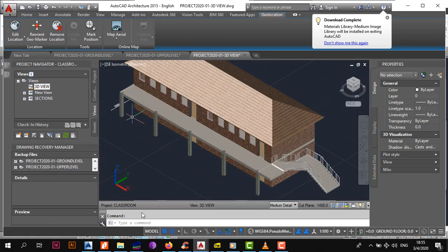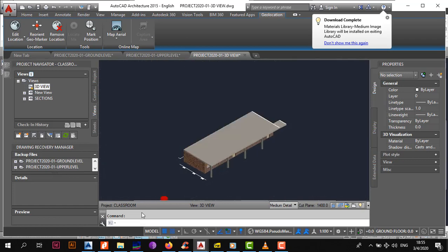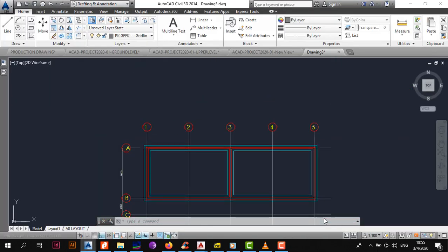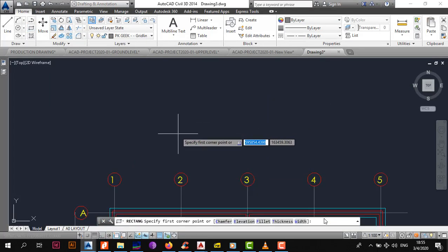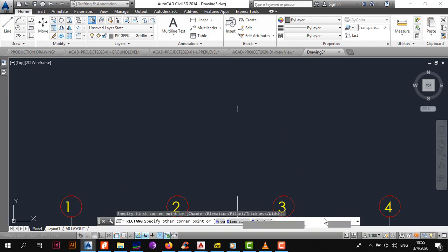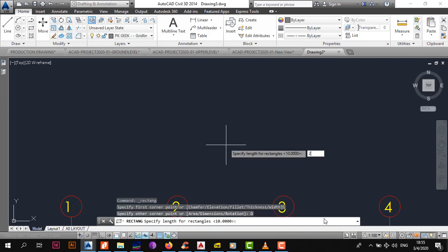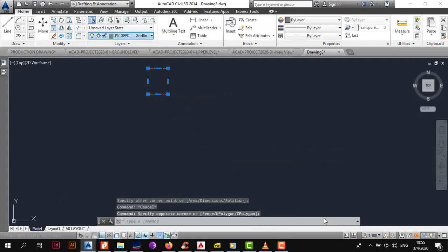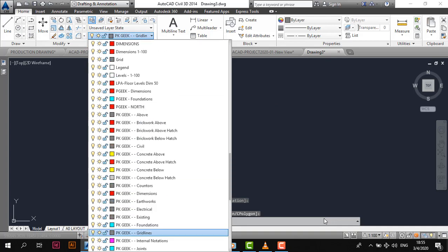And then obviously we already do have columns which are provided by the architect, which was me, my other split personality. So we now need to provide our columns. To do that, just go back to the previous drawing, and I am proposing columns which are going to be 230 wide by 300 wide.